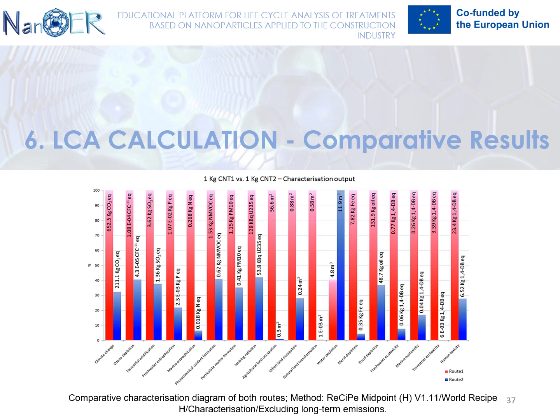Lastly, this comparative graph illustrates the effects of the two alternatives, giving the characterization values of each impact category. As it is observed, Route 1, the floating catalyst approach, has the highest impact across all categories. This fact is attributed to the higher energy demands needed not only for the higher growth temperatures, which is 850 degrees, but also for the supply of additional heating to facilitate the evaporation of the raw materials.